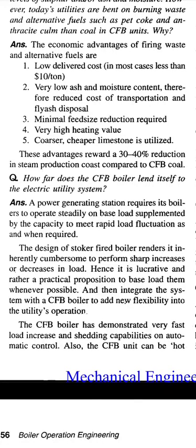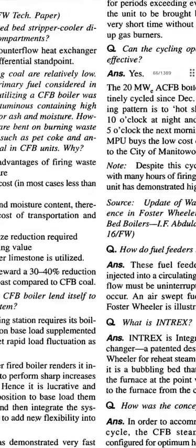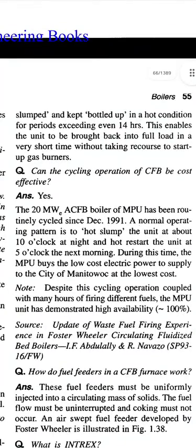The CFB boiler has demonstrated very fast load increase and shedding capabilities on automatic control. Also, the CFB unit can be hot slumped and kept bottled up in a hot condition for periods exceeding even 14 hours. This enables the unit to be brought back into full load in a very short time without taking recourse to start up gas burners.